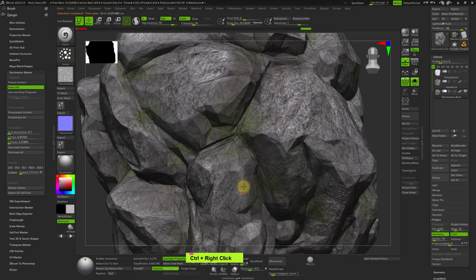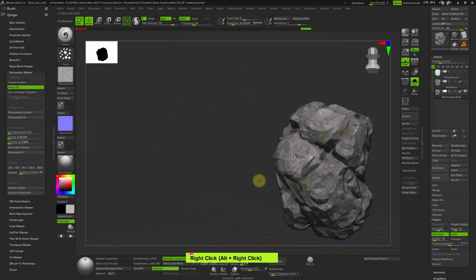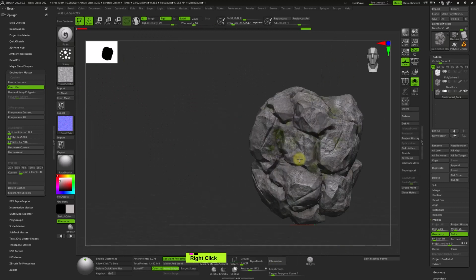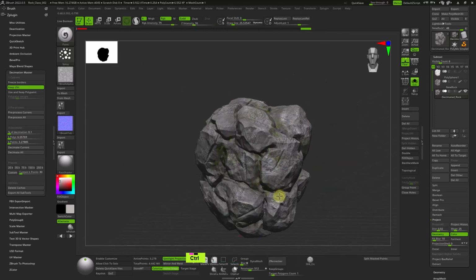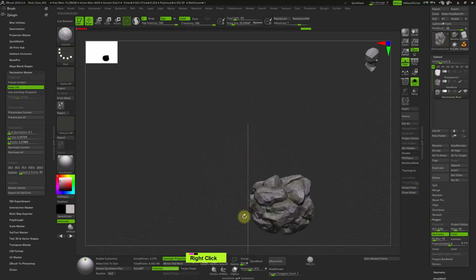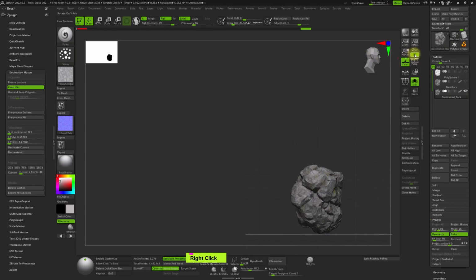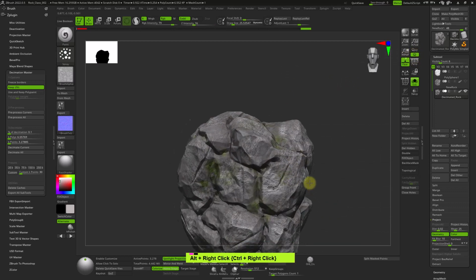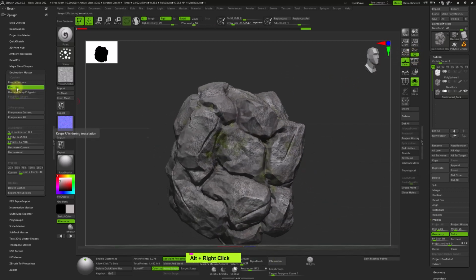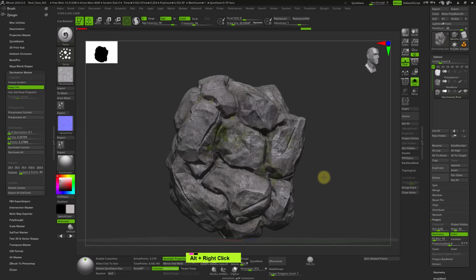This is 3,000 polygons, but this looks fairly convincing as a rock. Okay, especially in the distance. So you can create different resolution rocks for yourself. Let me just use the y-axis. So this way, if you have decimation and this keep UV is loaded, you can create low resolution meshes and